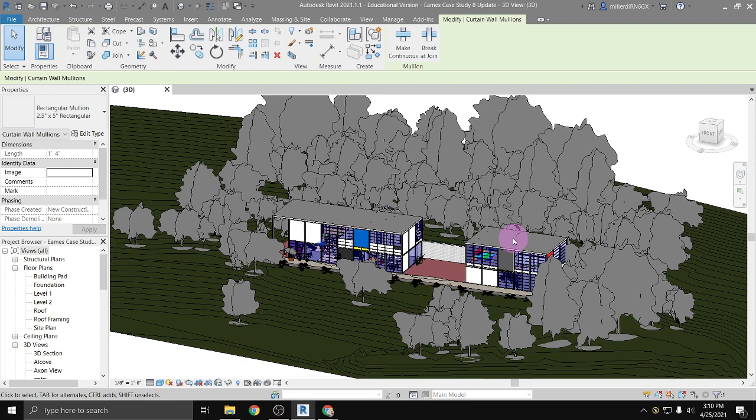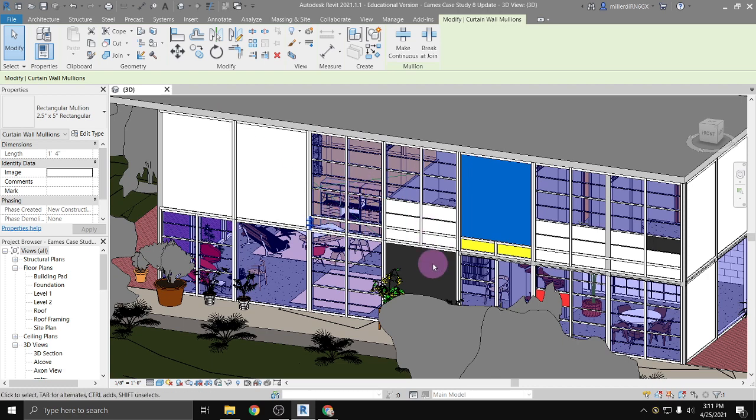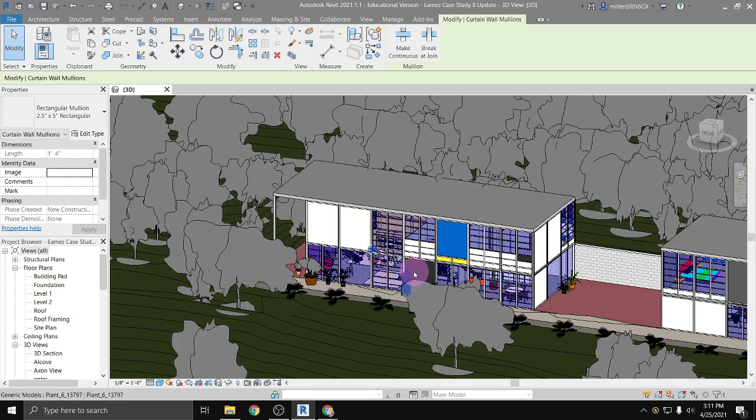The thing to consider though is that this building exists in Southern California. And so they are not too concerned with that heat transfer the way that we are here in Boone, because they want that air to be able to exit and flow out of the building rather easily. Most of these are also windows that can open so that air can flow through. That for them is very different from here in Boone, because in Boone, I want the tightest envelope to my building as possible so that in the winter I can spend as little money as possible on things like heating and cooling it.